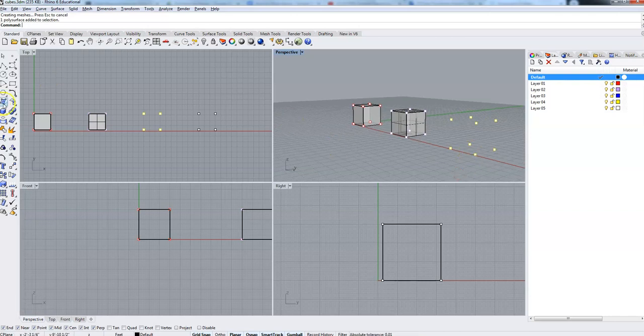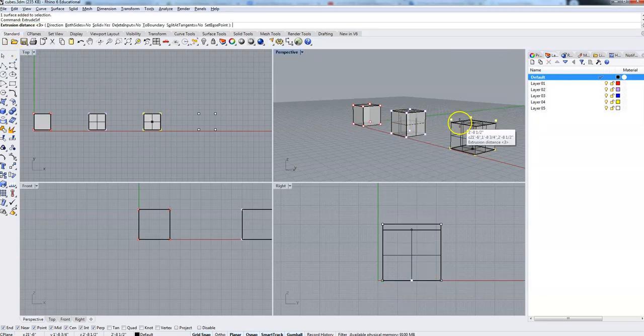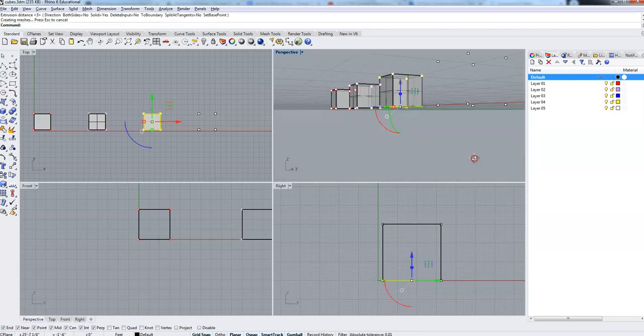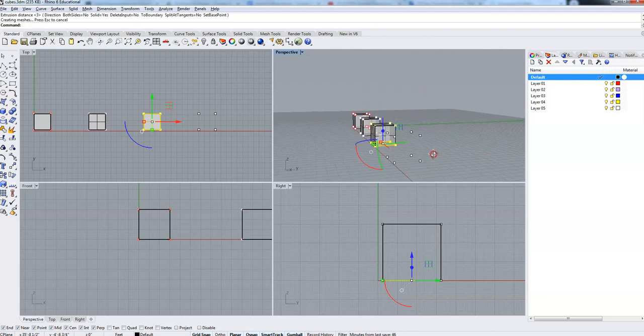All right, what if we started with a poly surface like this? Like a 3-point surface, bang. And that's how we started. Now, rather than extruding the curve, why don't we extrude the surface? So I'm going to select that and go up here and type in extrude. And you can see extrude surface is one of the options here. Bang. And look at that. Just like what we did with the curve, we can lock that in on the points, and we've got a nice cube there. Okay, well, we're just cruising right along here.